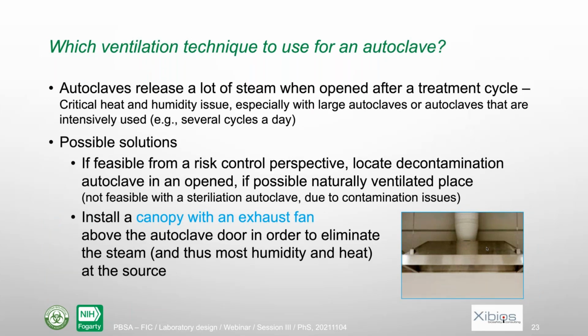Another question was related to that, which ventilation technique should we use for an autoclave? Actually, autoclaves release a lot of steam when they are opened at the end of the treatment cycle. So when you open the door after the treatment cycle, they release a lot of steam, which means a lot of heat and humidity.